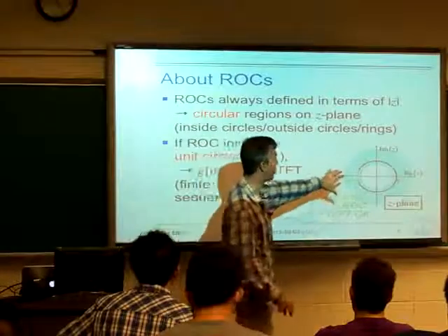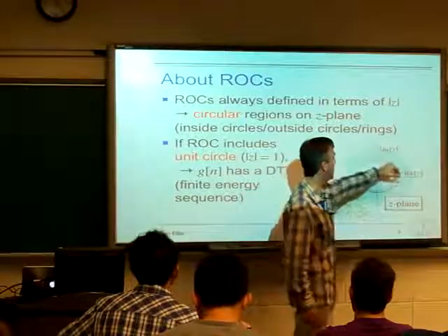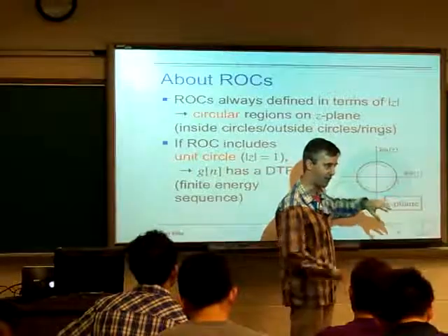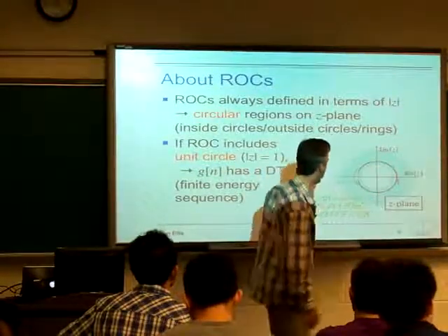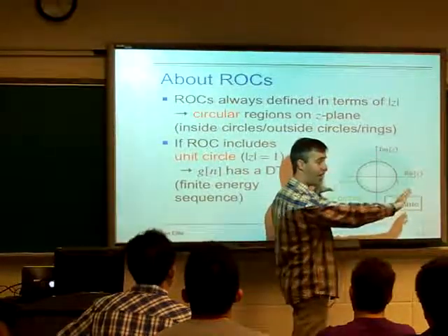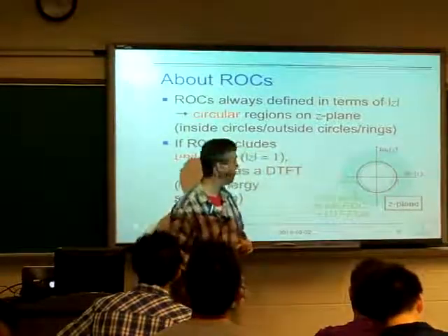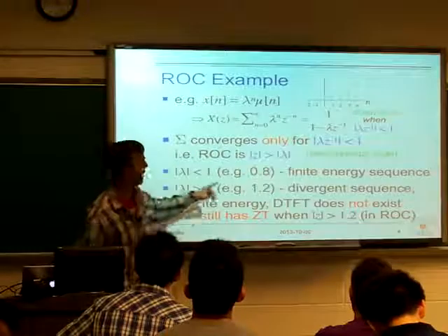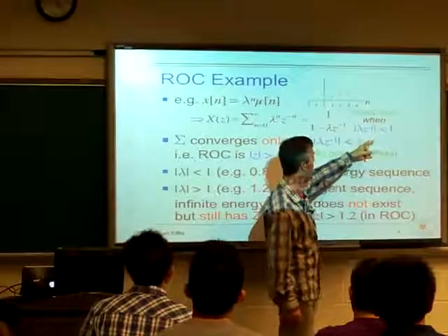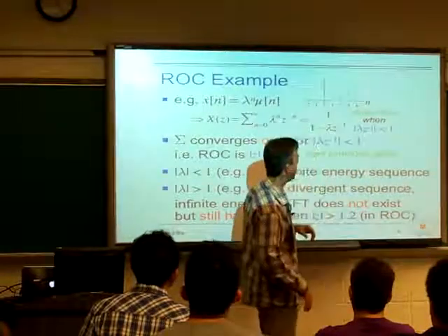And so typically we can draw it like this, that here's the whole z-plane. Now we're looking at that plot from above, and the shaded region is the values of z for which the sum converged, and then the blank values are the values of z where it didn't converge, and so they're the part that are not in the region of convergence. And this is the picture that we saw, right, that there was some circular region for values of z outside, larger than that circle, we were okay, and then for values of z inside, we were not. And that's exactly this case, right? So the constraint is that lambda divided by z needs to be smaller than 1. So as long as z is large enough, then that ratio will be small enough and we'll be okay.